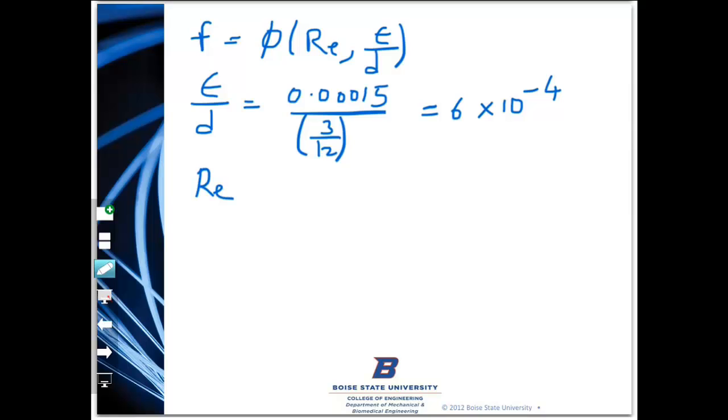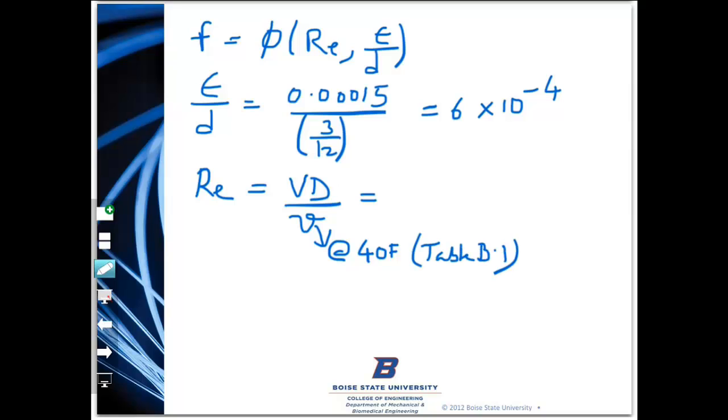And I can also compute the Reynolds number, VD over nu, and make sure you use the viscosity of water at 40F from table B1.